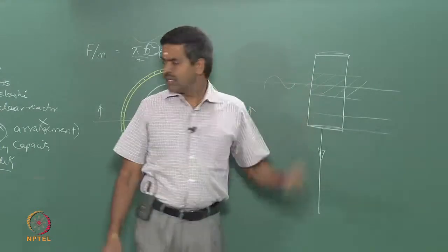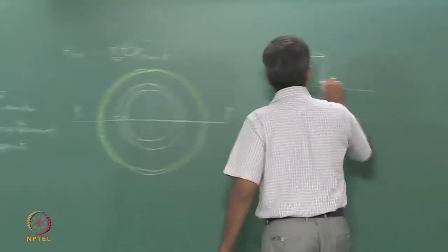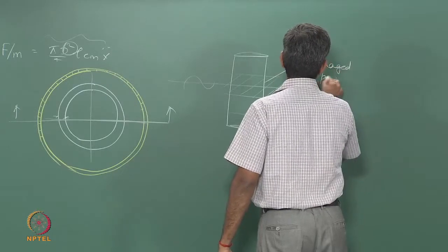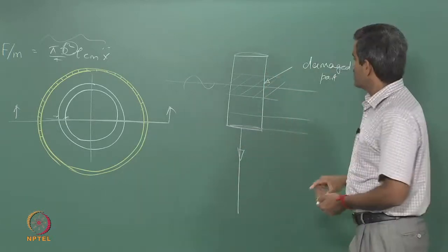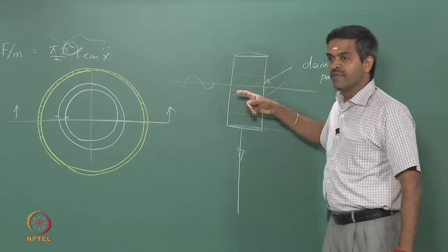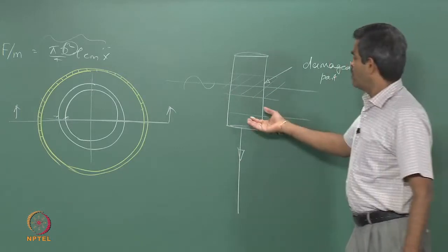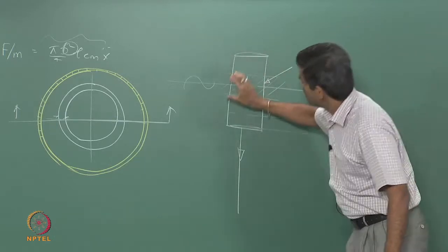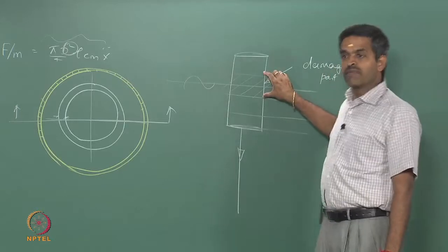When the material degrades, it loses its strength, we all know that. So, therefore, I can call this segment of the member the damaged part. Obviously, you will notice that the member is not uniformly damaged, because it is not uniformly corroded. We all know that there is a differential aeration. As you go deeper and deeper, the corrosion effect is practically 0. As you go higher and higher, again the effect is 0, because there is only aeration effect here. Only the alternate wetting and drying will create more corrosion. Therefore, this area is highly susceptible to corrosion.